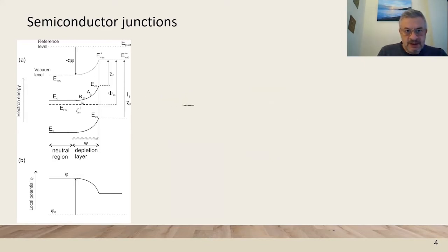So a semiconductor in the bulk region will have electrons in equilibrium. But when we arrive at the surface, it will be modified to be in equilibrium with the contact material, so that, for example, we can obtain band bending. And then we can see that in this region, there is much lower concentration of electrons than in the bulk, because the conduction band is far from the Fermi level.